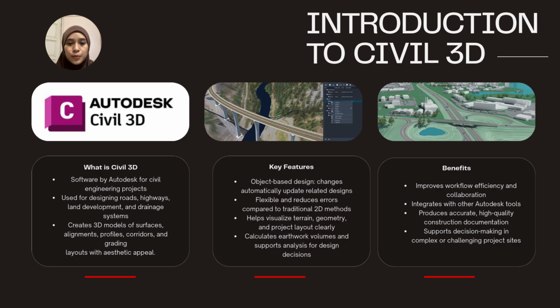One important feature of Civil 3D is object-based design. This means when we change one design, the other related design updates automatically. It is more flexible than 2D drawing and helps reduce mistakes. Civil 3D also helps us visualize the terrain and design clearly and calculate earthwork volumes.